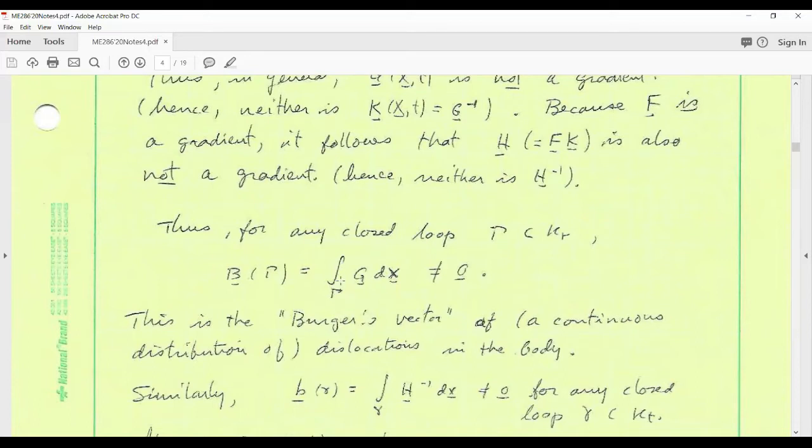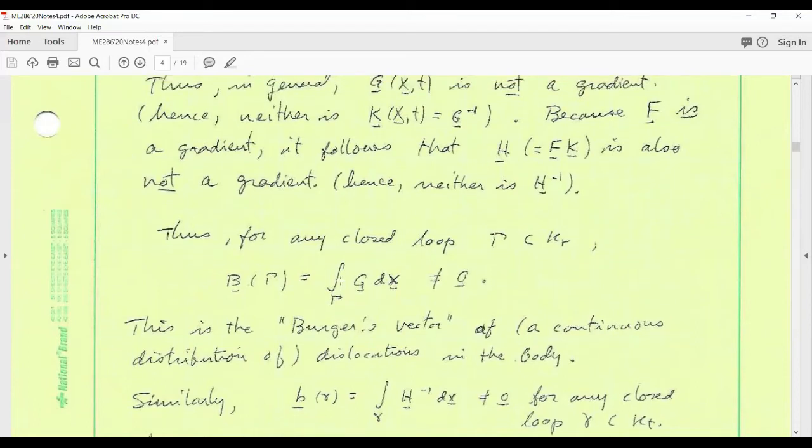Now, in this intermediate configuration, it's just a collection of, in principle, infinitely many discrete points, so that we cannot draw a curve in this intermediate configuration, right? Because you have a dust cloud of points, and there's no curve connecting them. In order to make a curve, you have to go into the vacuum in between those points. And that means you cannot construct a curve within the actual material in the intermediate configuration. You can do so in the reference configuration. And you can also do so in the current configuration.